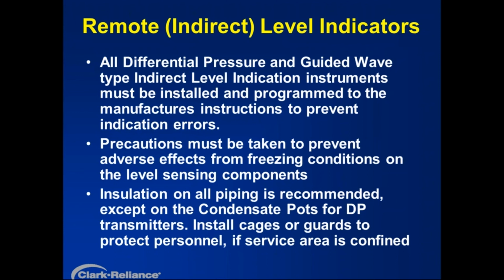beneficial to extend the life of a gauge glass, because excessive condensate formation can be sort of mimicking constant power washing on the inside of a level instrument or gauge glass, and if there's any particulate in that water, that could be raking across the glass or mica shield on the inside of those high pressure gauges, which in effect shortens the service life.